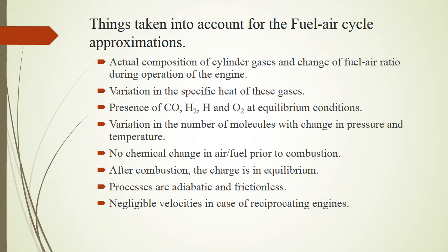The fact that the fuel air mixture does not completely combine chemically at high temperature, that is above 600 Kelvin, and that CO, H2 and O2 may be present at the equilibrium condition should also be considered. Also the variation in the number of molecules present in the cylinder as the pressure and temperature change. The number of molecules present after the combustion basically depends upon the fuel air ratio and upon the pressure and temperature after the combustion.